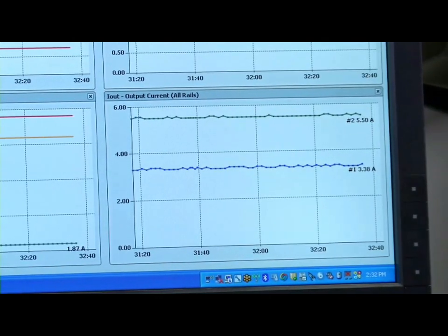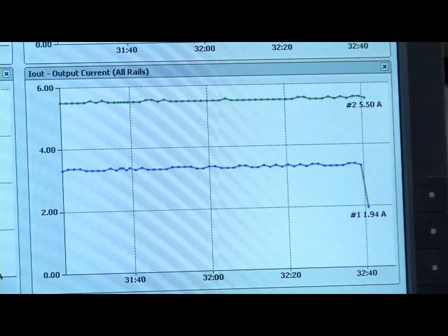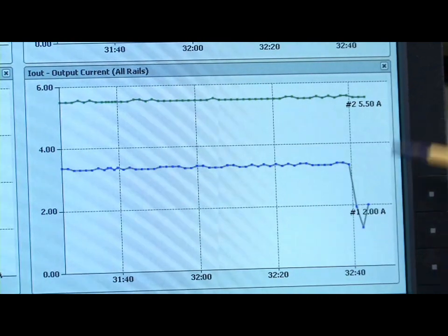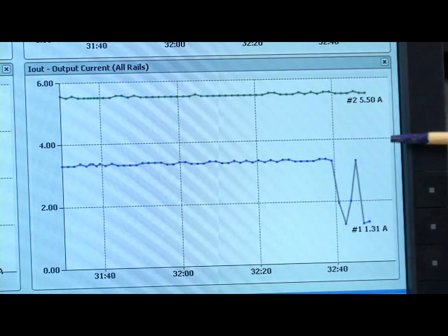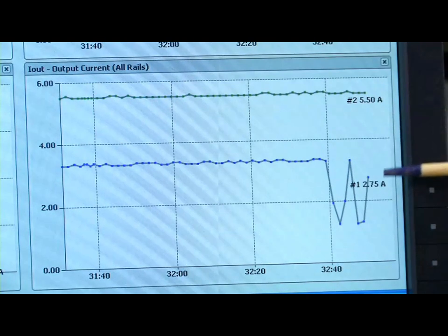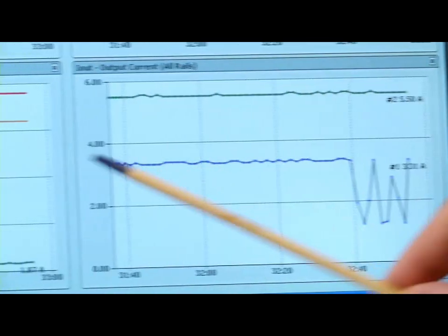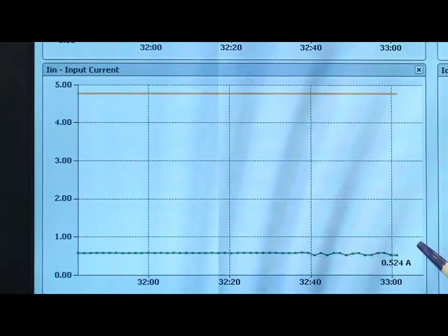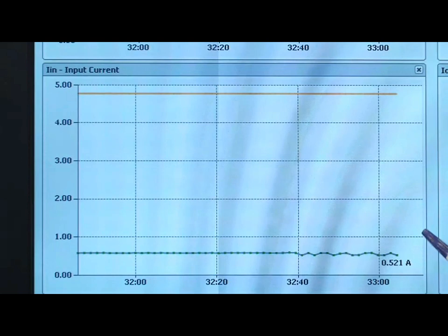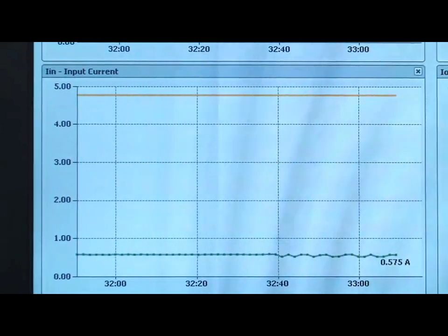But what I can do now is change my load on one of those output voltages so that we can monitor the difference, and we can see that dynamically as things happen in the system, we're visually representing that change on the GUI. So then let's take a look back at the LM5066 output, because as you can see over on the left, as we've made those changes to the load, we see that the input current coming into the system is now varying, something that we would expect.